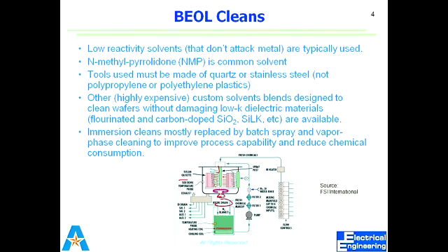For these low reactivity solvents, we should have either quartz or stainless steel containers. That makes these solvents more costly as compared to the front end of line cleanup process. So it makes it highly expensive.